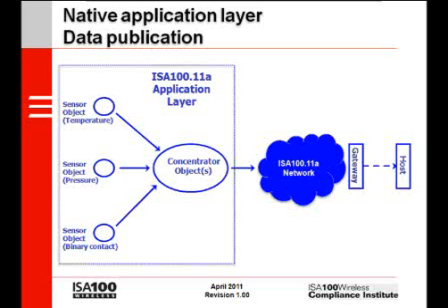The host, through the gateway, receives these three readings periodically, such as every 10 seconds. This is all accomplished by configuring a standard ISA100 concentrator object in the device. This is just one example of the capabilities of the native ISA100 application layer.